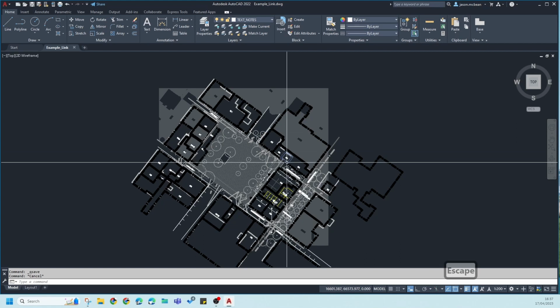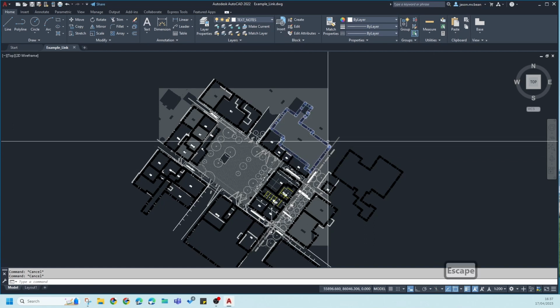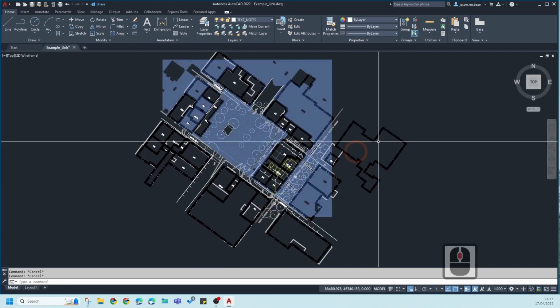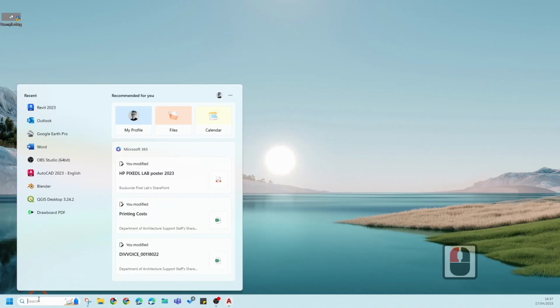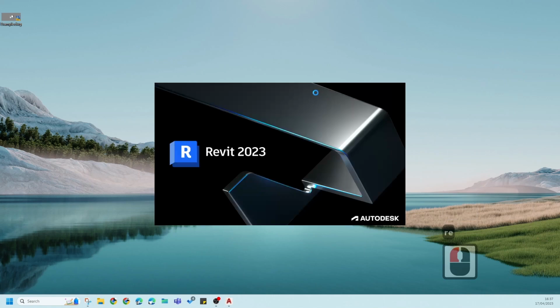Now try and put all this information in the right folder, and we'll explain that in a minute, once we start working with more of a central file type arrangement. We'll start looking how this works. So I can leave this file open now, and I'm going to leave this just like it is. Now, the next step we'll do is we'll start Revit. So launch Revit, and we're going to start a new project using our template files.